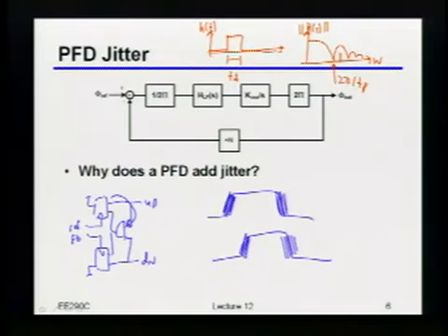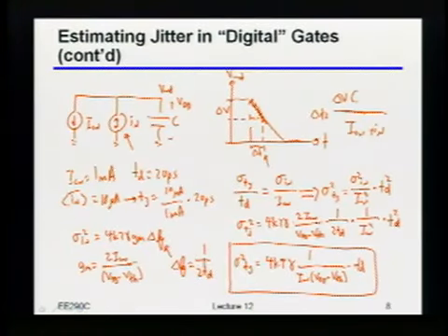The only trick is, where did that factor of 1/2 come from? That factor of 1/2 comes from, if I add up all of the spectral components because of that sinc filter, altogether they normalize out to become a bandwidth of 1/2. Okay, that's just where that came from. So again, the math is actually not that complicated. You literally just integrate this sinc function from 0 to infinity, and indeed, this is the result you get.